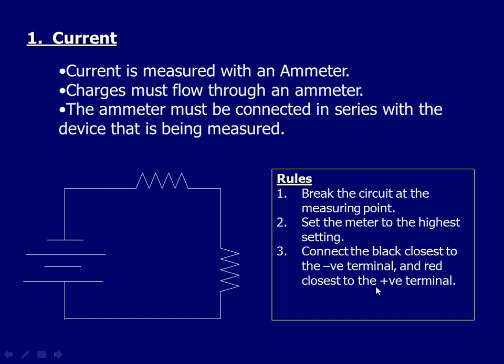So, again, black connected to black. First, connected to the 5. I turn the power on. I notice that the meter hardly moves. I shut the power off and I move it over to 500. I turn the power on and I notice it moves just below halfway.